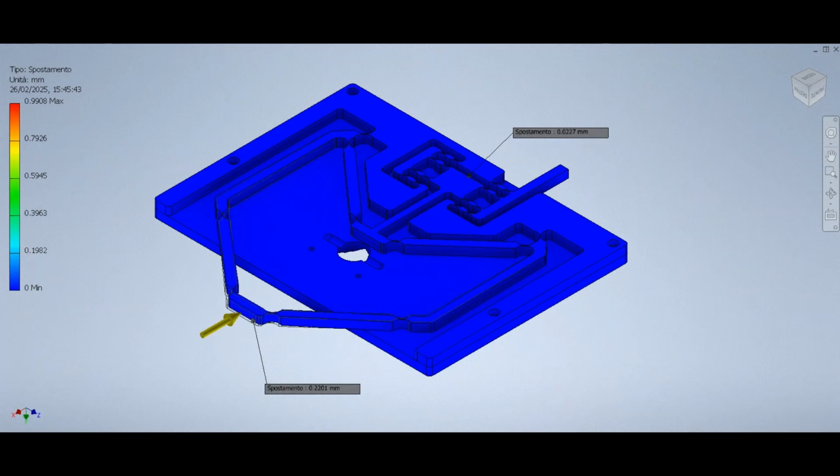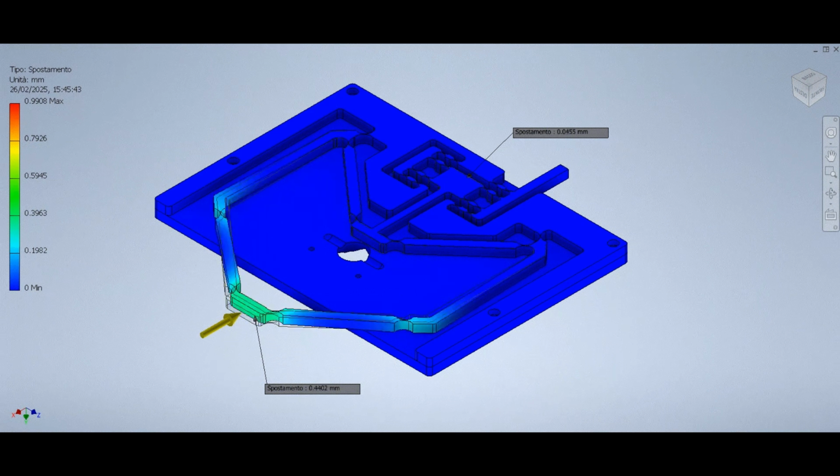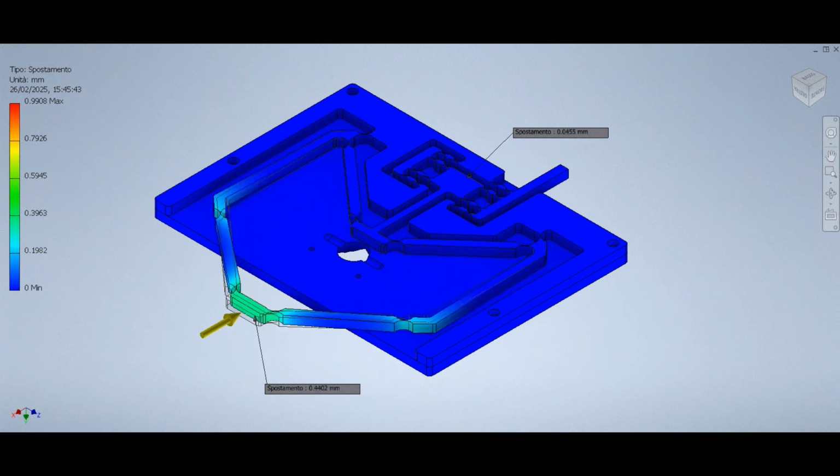The mechanism was subjected to a stress and displacement simulation using Autodesk Inventor. The analysis was performed by first applying constraints near the V-grooves, imposing absolute fixing constraints to simulate the Kelvin clamp. Additionally, collinear constraints were assigned to the holes of the screws that fastened the two plates together. Along with the constraints, a concentrated force was applied to the input plate. Furthermore, specific points of interest were defined, for which the displacement relative to their initial or resting position was subsequently evaluated.